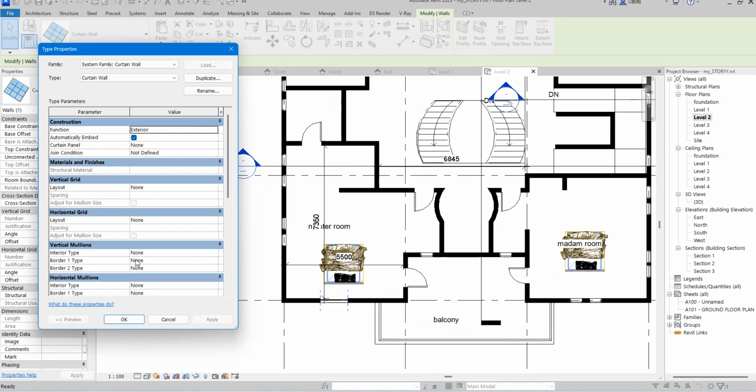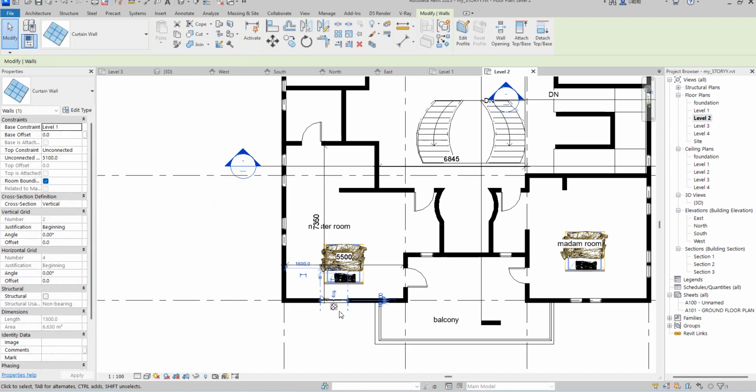So what I'm doing here is I'm going to give a vertical spacing, which is going to be a fixed distance. So I have 17. I'm going to do 650. Yes. So mullion on vertical, you can select that one and put 1 there. Just look at the one that you know is okay for you, but I'm going to use this one, the radius circle. Let me just use that.